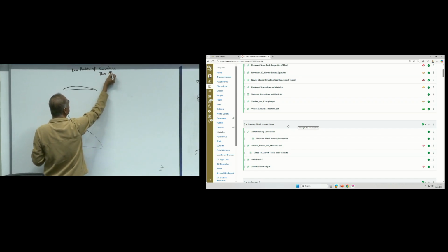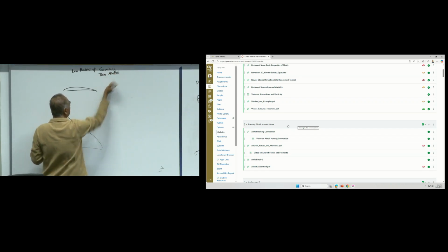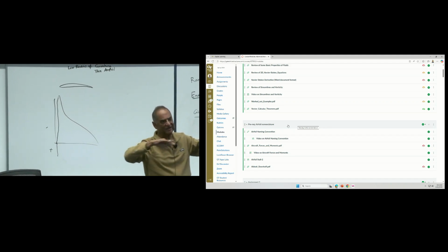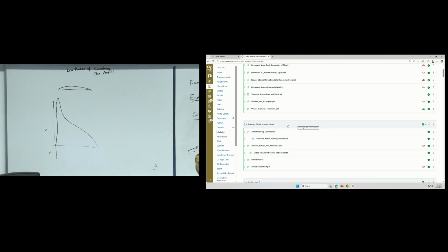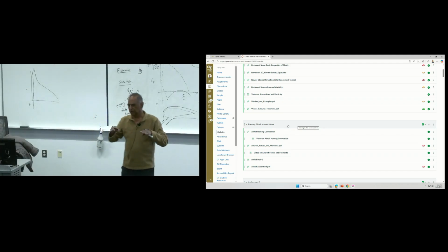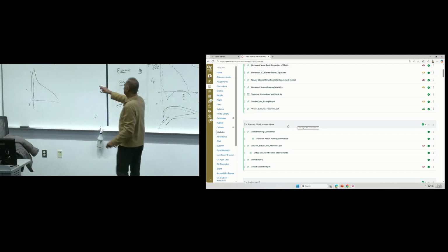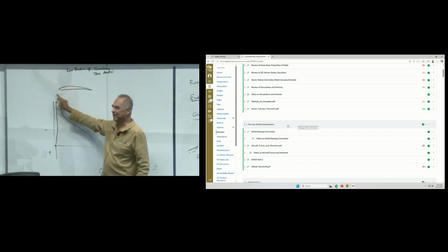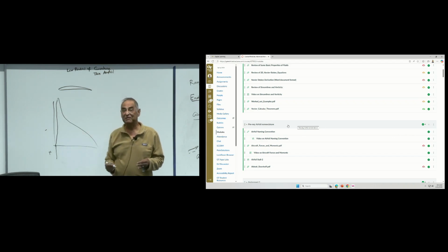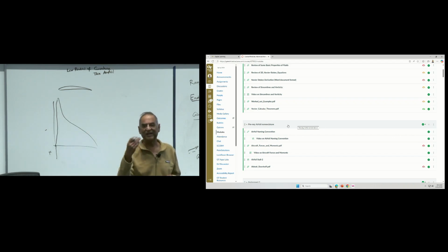Usually a very thin airfoil. Remember gliders, people were making them in the early days, almost zero thickness, but it did have some thickness at the leading edge, like the Wright brothers did. So think of it as a very thin fabric with some kind of a blunter nose, if you will. Now, this pressure gradient is so adverse, it may separate before transition occurs, coming back to Felix's question.